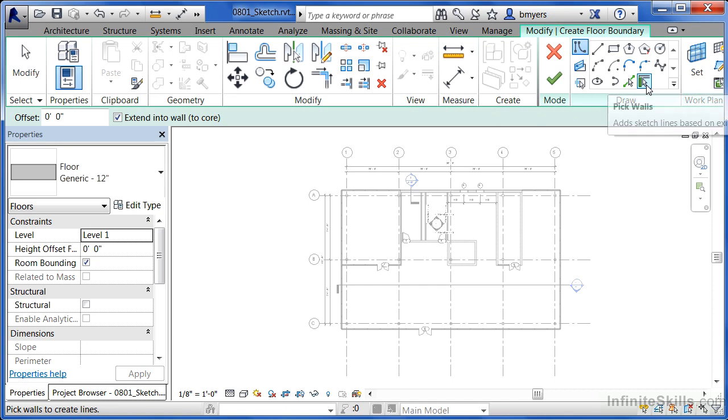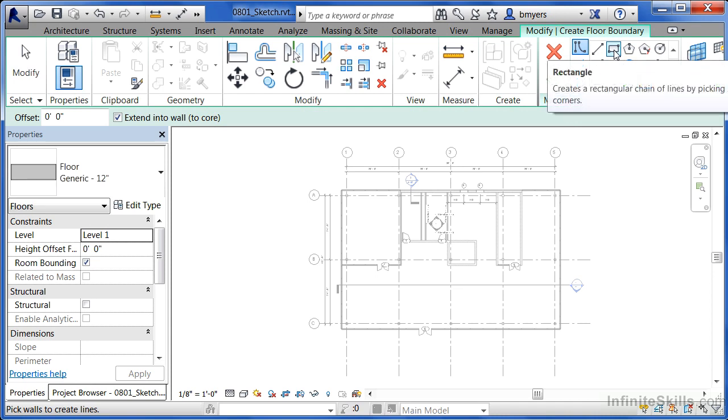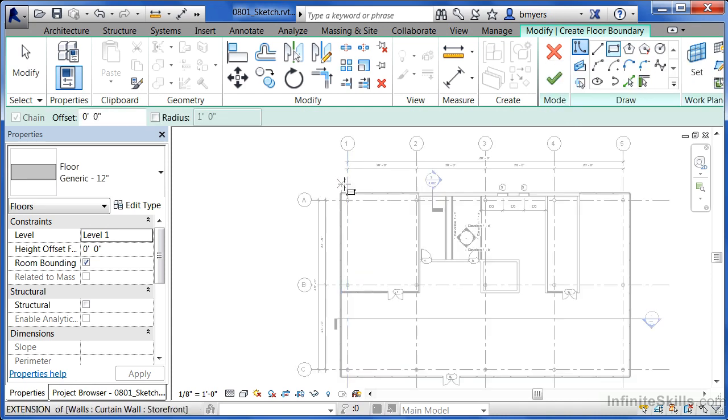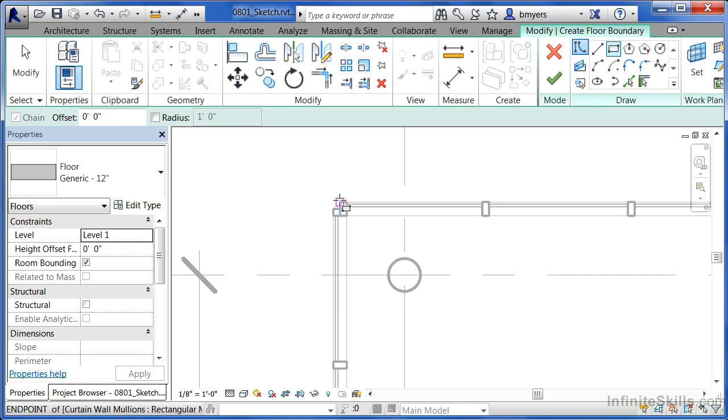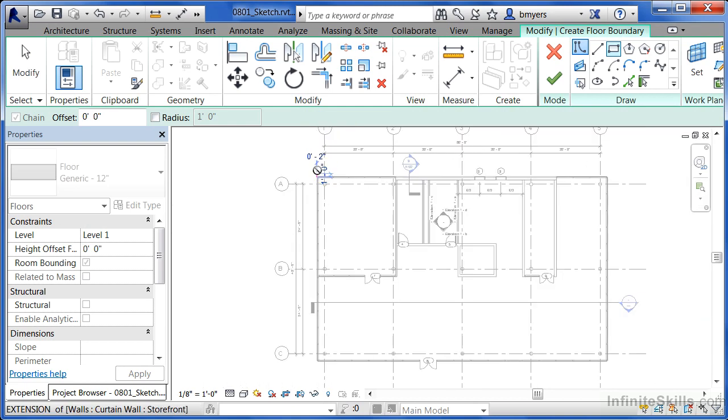Check your drawing tools. And what we're going to do is we're going to draw all the way around the perimeter of this with the floor. Now, structurally speaking, this probably isn't the best thing that we could do. But just to demonstrate how floors work, this should work really well. Move up here and select on the Rectangle tool. And you notice that you can't really pick on the intersection of these two spots very well. So just click at the intersection of one of these. We'll adjust it after the fact.